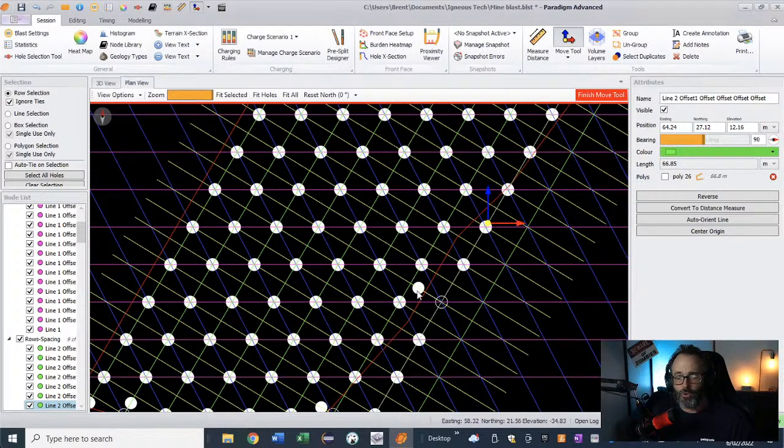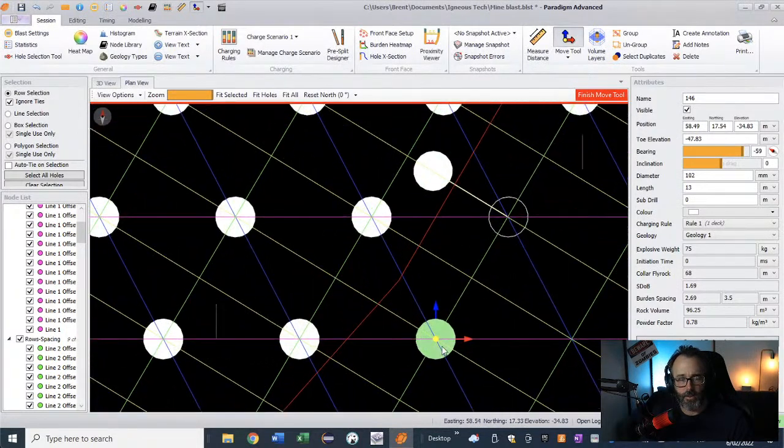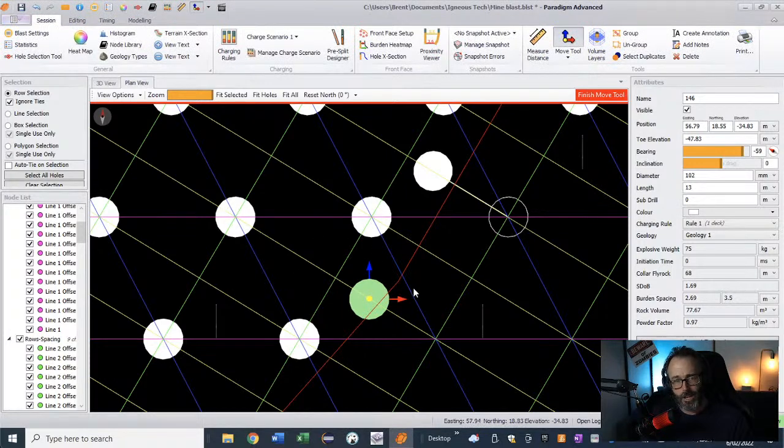You don't want to be using angles if you don't need to in broken ground. If you've got a quarry and it's a very firm rock, very uniform and not broken, then angle holes are fine. But they are more effort, they do deviate, and so they come at a cost, essentially. Now, you can do the same if you just want to give it a bit of juice on the face. You can use the same mentality there and not even angle it, but I know the hole needs to go back along that line, in the line of the stagger.